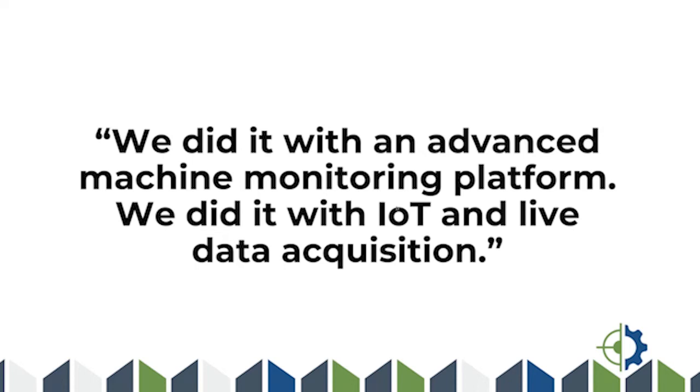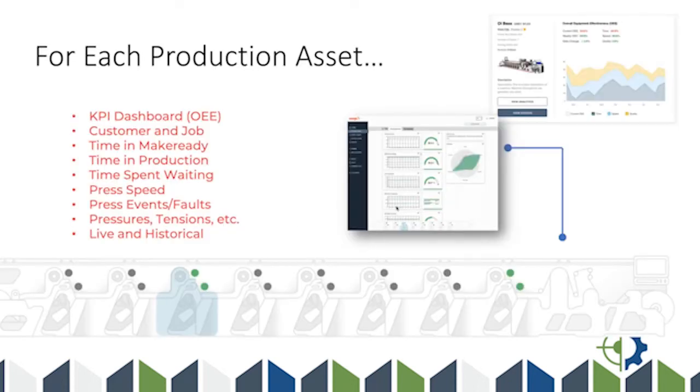And so what does that really look like? For every production asset that you've got, from the press itself to the connected peripherals, it's really starting with the idea of data points, gathering data. There's a new vocabulary word that we'll throw out today called telemetry. The data telemetry that can be gathered from a machine. It starts with really basic KPI stuff: the machine speed, its status, is it running, how fast it's running, is it making sellable product or is it not, is it stopped or is it in make ready stage, et cetera.